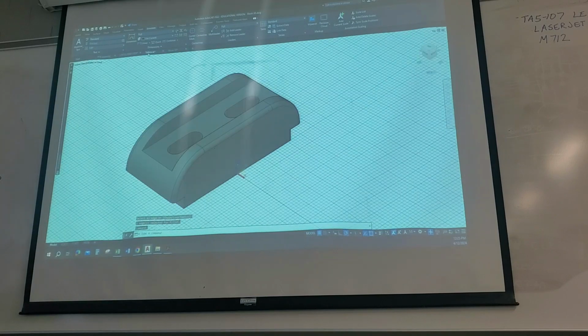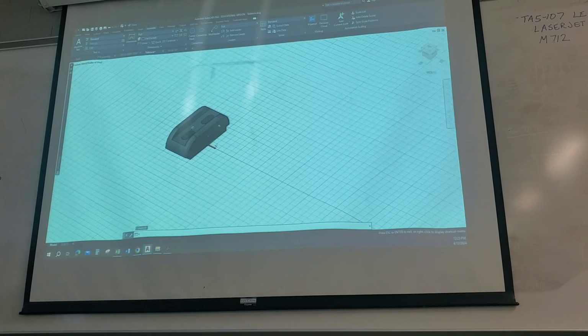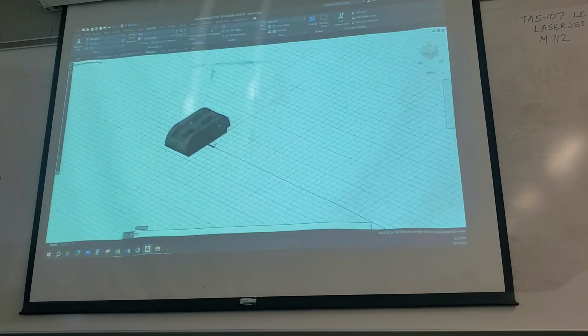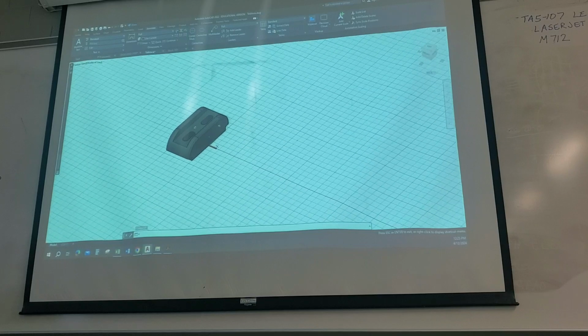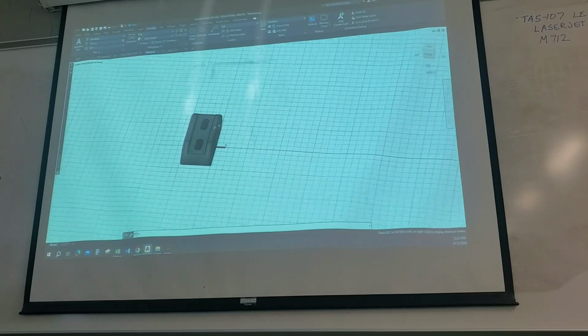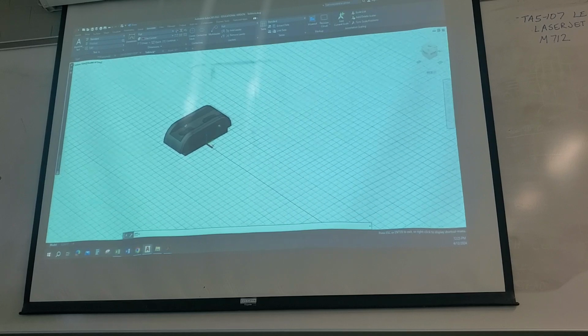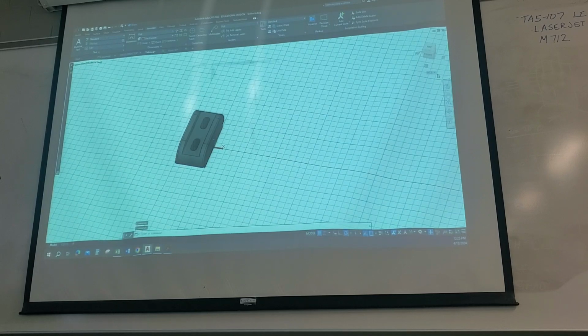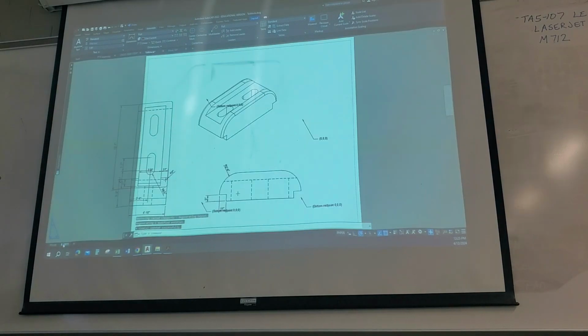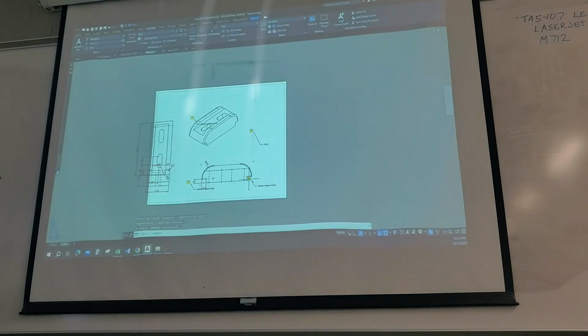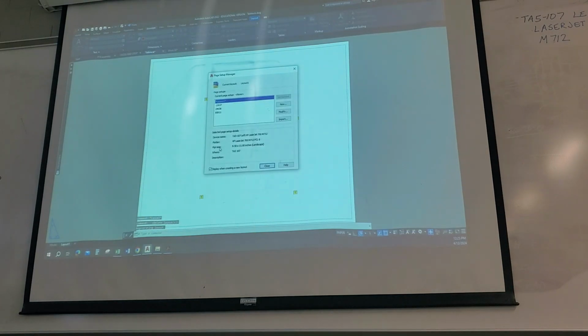So your first one is the tailstock that is centered right there at the middle of that side, the midpoint of that side. So once again, when it comes time to turning it in, that drawing needs to be right there at 0, 0. You need to have WCS locked in up here at the top right. So to finish this project, you'll come down here, pick your border and title block, 8.5 by 11. Looks like I already been playing in this one, so I'm gonna delete that one. Go ahead and make me another one.